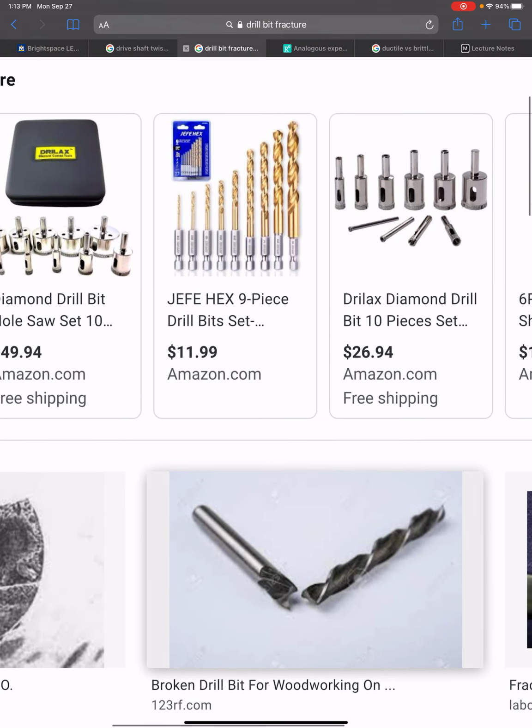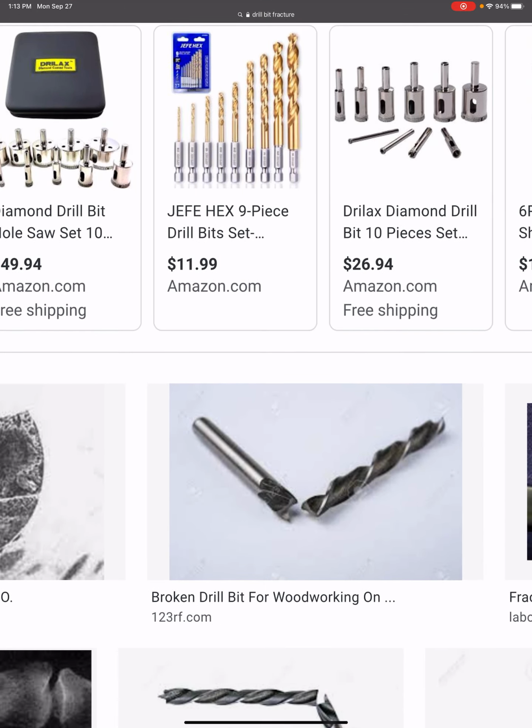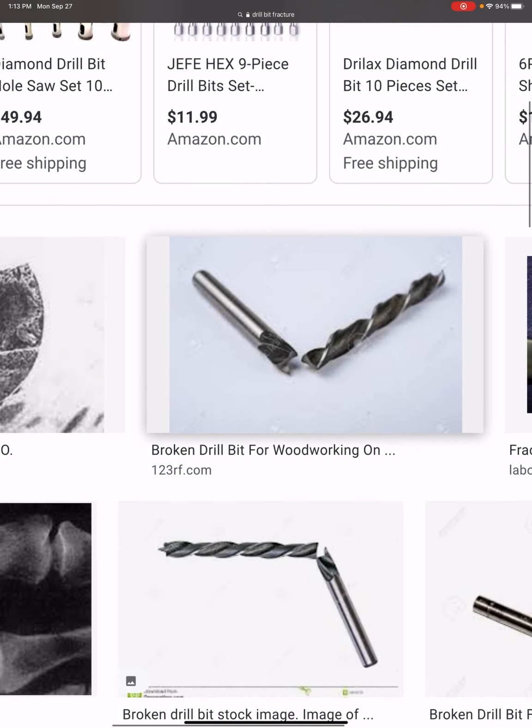Another one is drill bits. Okay, I'm sure all of you guys have tried to drill a hole with a very small drill bit and that thing snaps off. Well, after you decided to throw the thing away, if you were to actually pick it up and look at it, drill bits are very brittle because they're hard generally, and because they're very brittle, the drill bit will actually fail in a 45-degree angle spiral, which is neat.